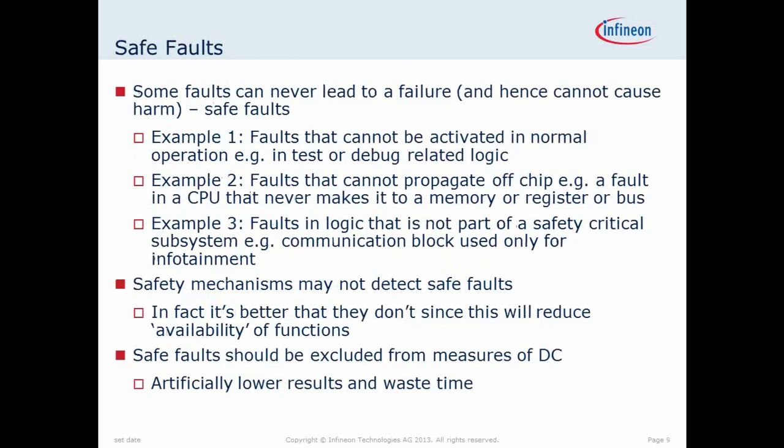So now I come on to safe faults. Some faults can never lead to a failure, and so they cannot cause harm, and these are called safe faults. For instance, faults that cannot be activated in normal operation. If you have a fault in your test or your debug logic, this is typically turned off during normal operation, and so faults in there typically aren't going to lead to any kind of failure which can cause harm.